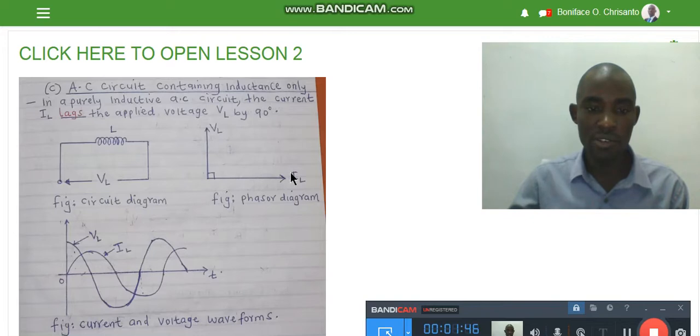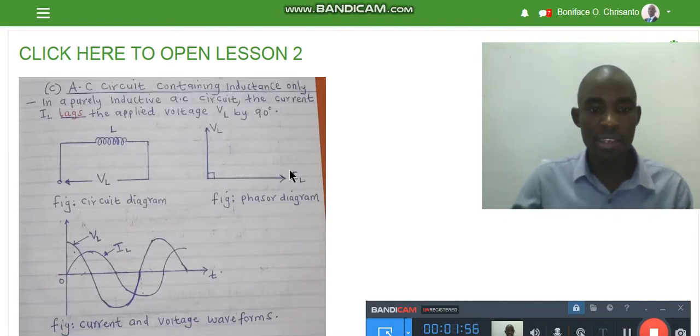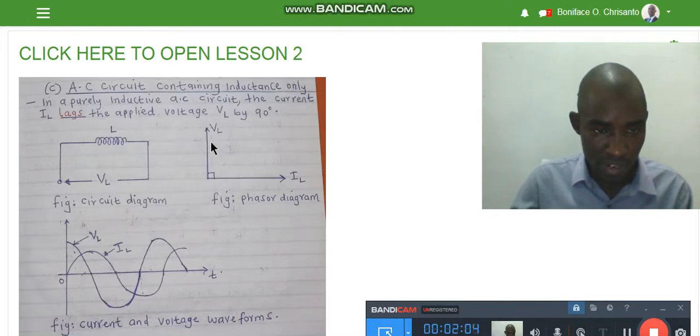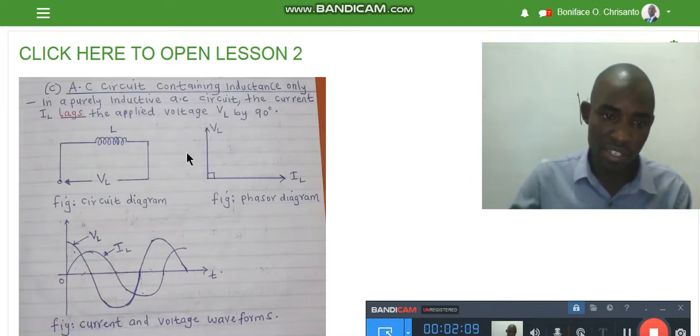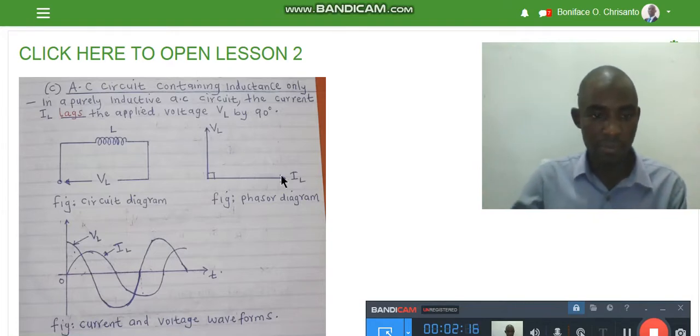Once you draw current on the horizontal scale, and we have said voltage is leading, in an inductive circuit, voltage leads current. In other words, current lags behind the voltage. So because the voltage is ahead by 90 degrees, you draw it vertically. If you measure from the current to the voltage, the angle between them will be 90. That is why we have 90 degrees between the voltage and the current. So this is the phasor diagram of an inductive circuit, and this is the circuit diagram.